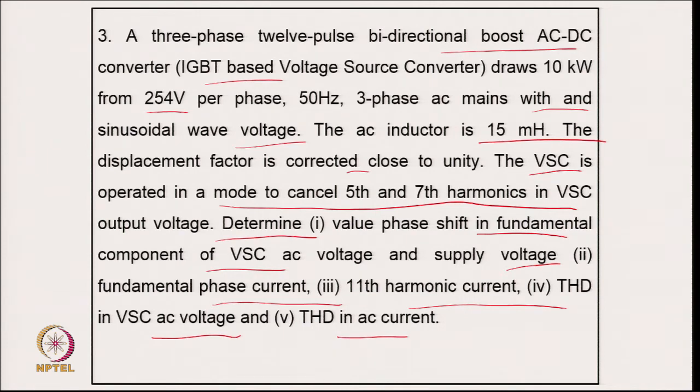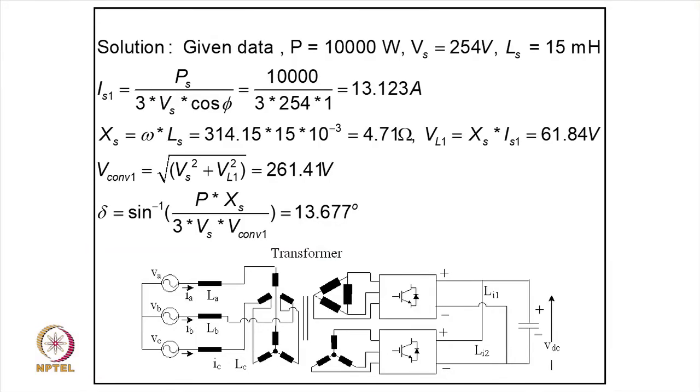So, what we are having here is typically a 12 pulse converter, and the difference here is that on the grid side we are connecting the transformers in series, and on the load side we are connecting them in parallel, because we want to apply the same DC link voltage. So, we are using 2 voltage source converters. We can of course either feed the load here, or we can have even solar injection or bidirectional power flow in this voltage source converter.